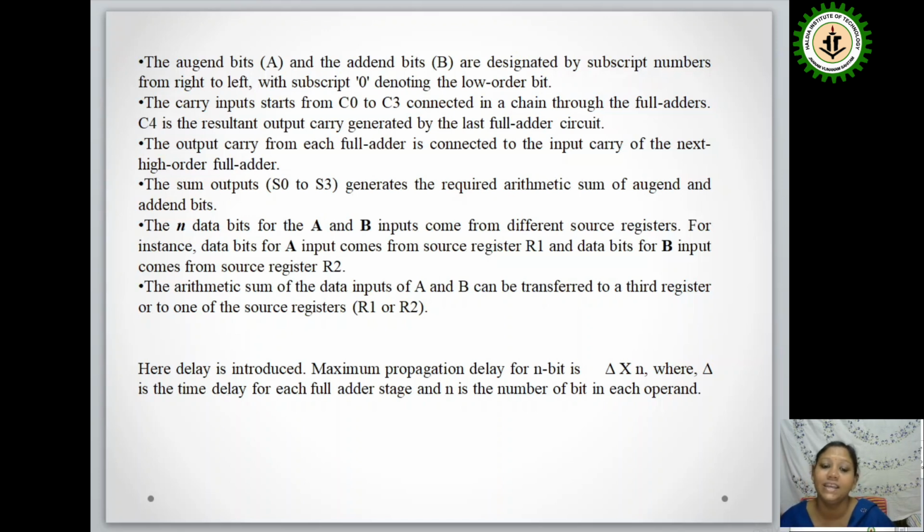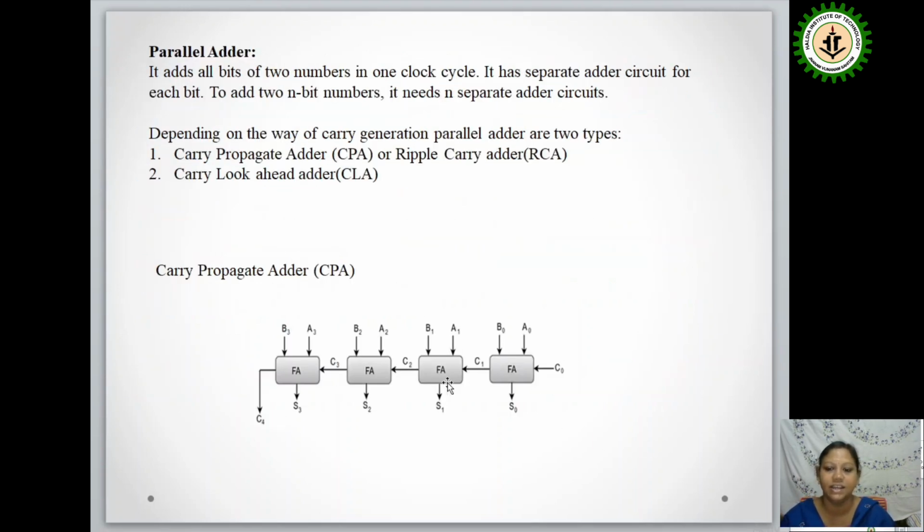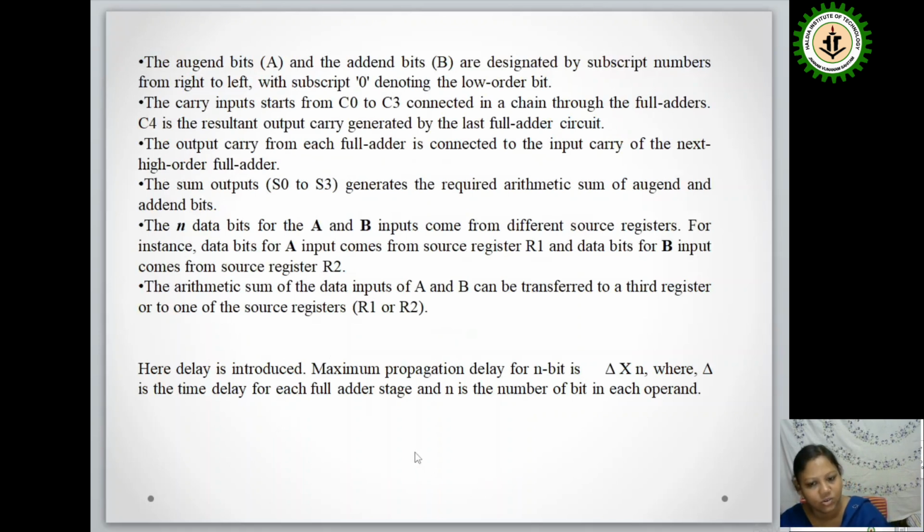Now, most important, here delay is introduced. Why is delay introduced? Because the next full adder depends on the previous adder circuit's carry output. Until C1 is generated, the second full adder cannot start its execution, because C1 is taken as the third input to that full adder circuit. So that's why delay is introduced.